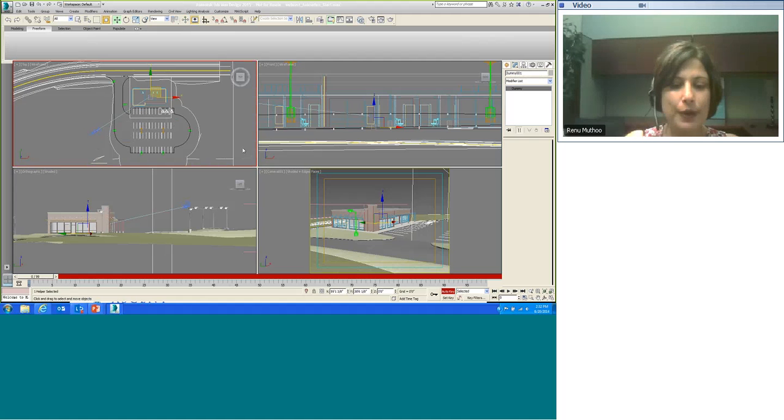So for a turntable, it needs to be revolved 360 degrees around its pivot point, which is along the z-axis. We don't need too many keyframes. We will just set 3 keyframes in addition to the 0 keyframe, which is the starting point. So we will divide it into 3 equal keyframes.